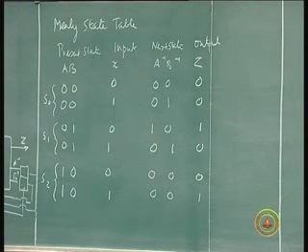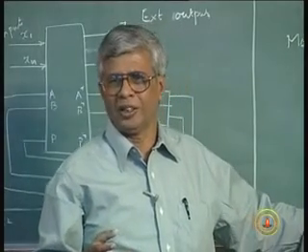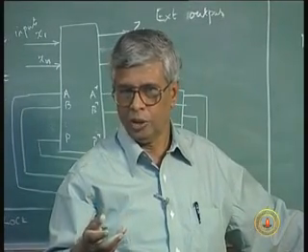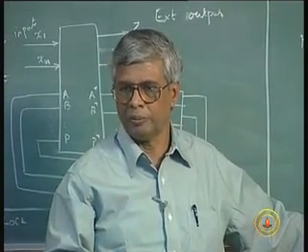I will not write Z's as arrows along with the arrows. I will define Z's inside the state circles, because in a Moore machine output is defined for each state, which is similar to a counter. Now, for example, in a counter, each state is a count. A counter is a typical example of a Moore machine.